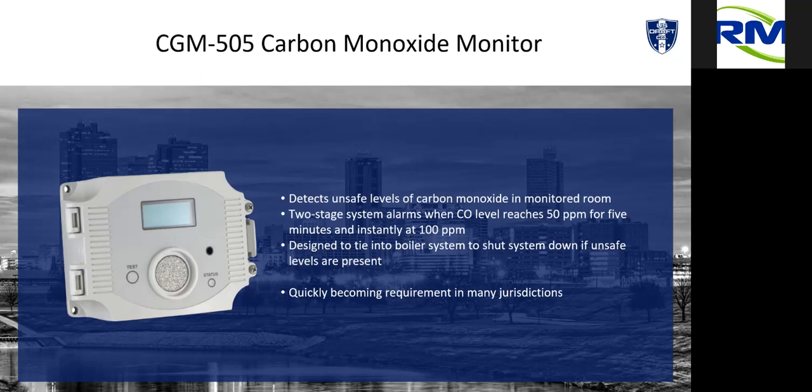So stage 1 is set at 50 ppm. If it gets above stage 1, it turns on a timer. That's adjustable from 3 to 5 minutes. If it stays above that level for that timer, it shuts off the appliances. Manual reset. If it gets to stage 2, it immediately shuts off the appliances. It's factory set at 100 ppm. It immediately shuts those appliances off. And again, it's a manual reset.